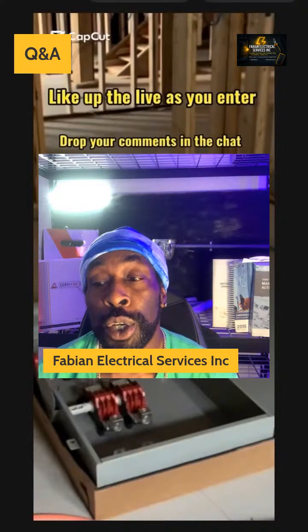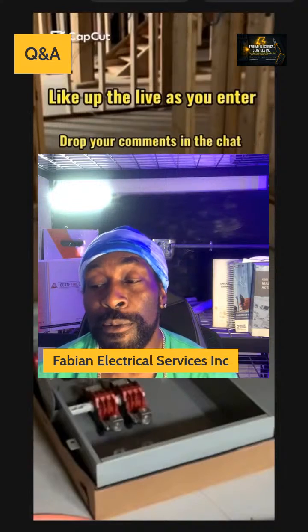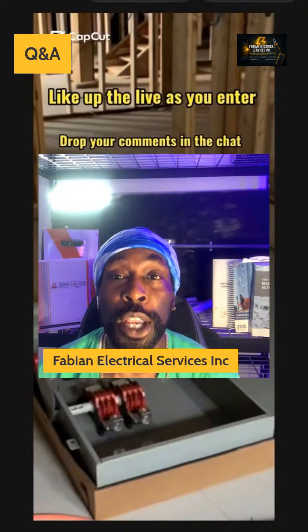That means your heavy conductor that was safely rated for 100 amps can suddenly only carry 58 amps before the insulation completely melts down. If you don't upsize your wire gauge here, you fail your inspection.